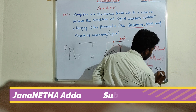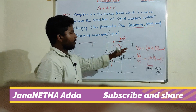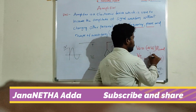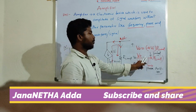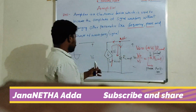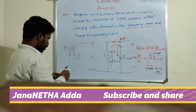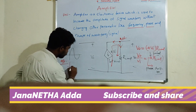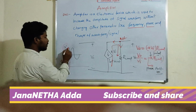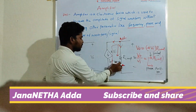of 180 degrees. So what we got is a scaled version of the input with a phase change. If I draw the same signal, I am drawing the output at this place. So the output is scaled. I am assuming the input has 1 volt, and the gain of the signal is 10.